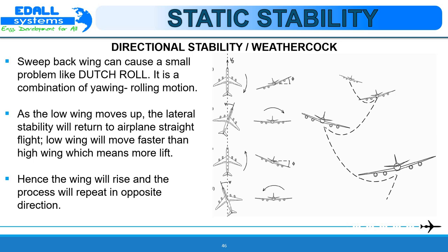The physical situation applying in a Dutch roll disturbance can be appreciated by imagining that an aircraft is restrained in yaw by a torsional spring acting about the yaw axis Z. The spring stiffness being aerodynamic and determined largely by the fin. Thus, in straight, level trimmed equilibrium flight, a disturbance in yaw causes the aerodynamic spring to produce a restoring yawing moment, which results in the classical oscillatory motion called the Dutch roll.